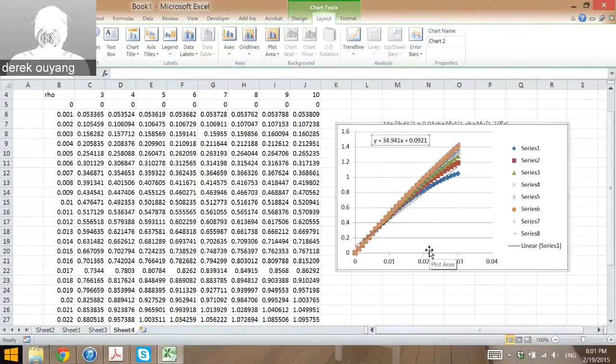It doesn't really matter what your f'c is, right? These are so darn close to each other that for a given 0.8, like let's say your moment normalized value was this, came over here, it would barely be changing your reinforcement ratio. Maybe even to the point that when you got that value and then you picked the real rebar choice, it would round up enough that it really wouldn't matter whether you had 3 versus 4 KSI. Hopefully that's just a learning point, right?